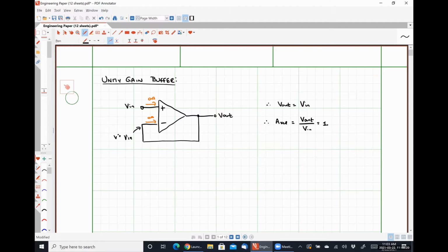So if we had a very sensitive sensor, say a pressure transducer or something like that. A pressure transducer is a device which converts a change in relative pressure, usually due to a fluctuation in the position of a diaphragm, into a small output voltage. Typically speaking, they cannot generate a lot of power. They generate reasonably large voltage signals, but can generate extremely small currents.